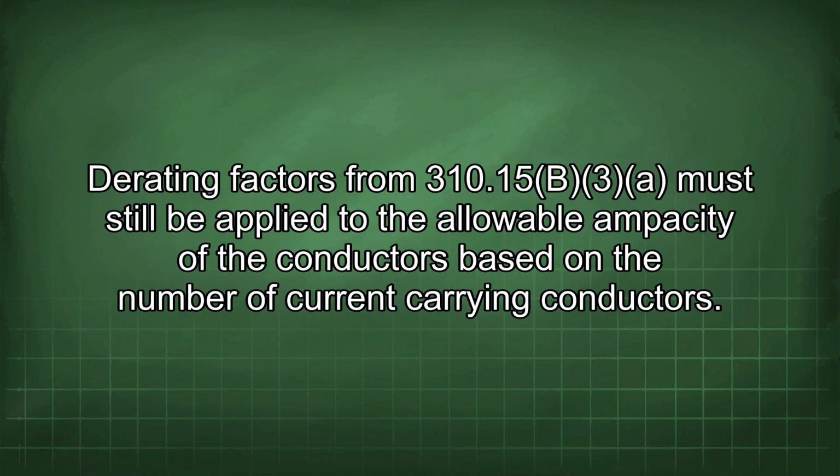Derating factors from 310.15(B)(3) must still be applied to the allowable ampacity of the conductors based on the number of current carrying conductors.